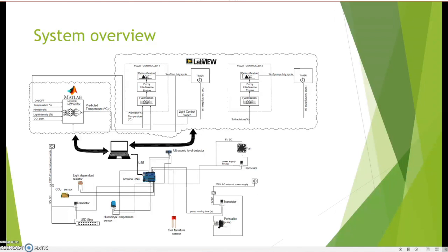Since our aim with the project was to design a fully automated system that would have graphical features with trend logging and give the operator the possibility to interact with the system, it quickly became apparent that using only the Arduino platform would not be sufficient. For this purpose, we have added LabVIEW as an additional software platform. The raw sensor measurements from the Arduino are sent via a serial channel into LabVIEW and used for control and monitoring of the system.